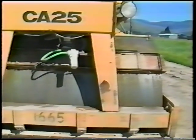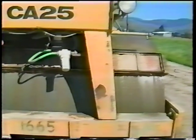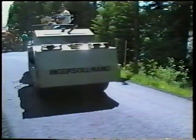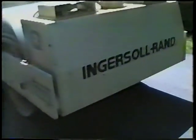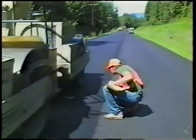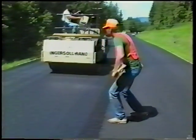The drums also have to be kept moist, so make sure all the sprinkler nozzles are working. And finally, look under the roller. Make sure there are no oil or fuel leaks. Either kind of leakage will contaminate the mix. And that covers steel-wheeled rollers.